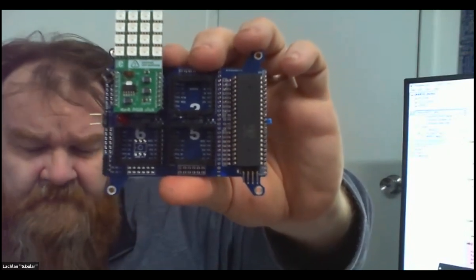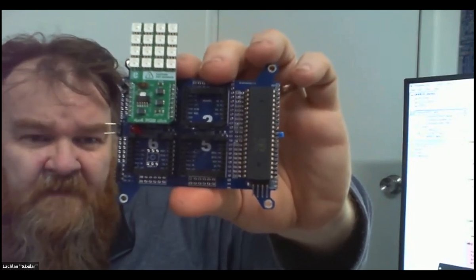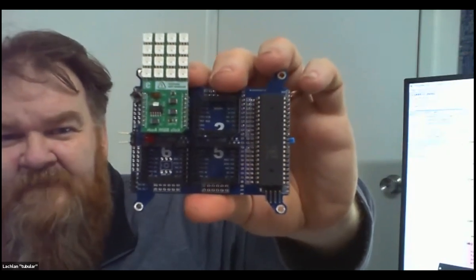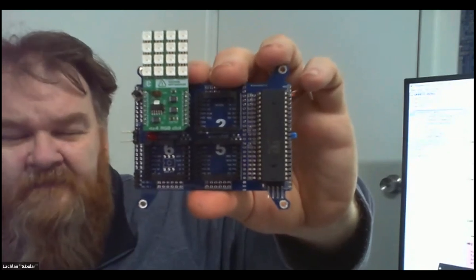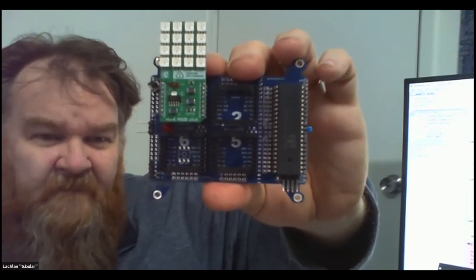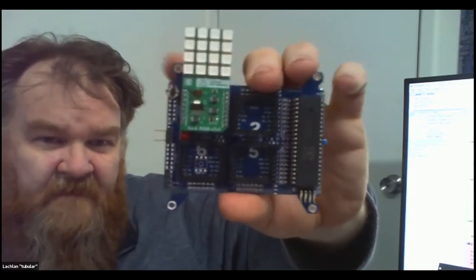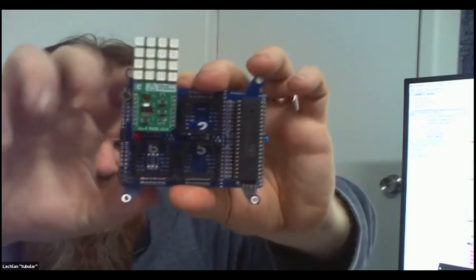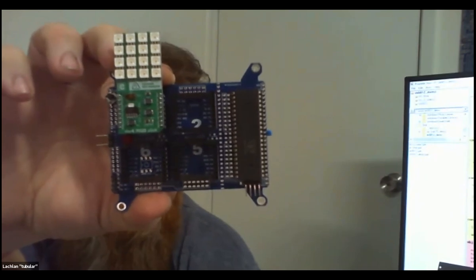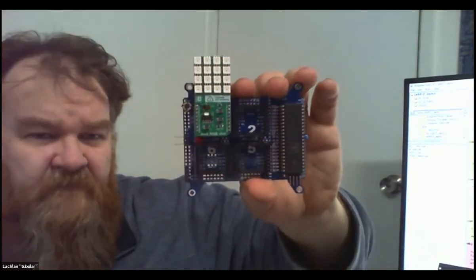And so with the P2, Chip was far-sighted enough to put in that right into the loader so that when you're doing a prop text or a prop hex loading command, you can set an address mask, and that means your code will only go to a particular module or a few modules which have a matching address which match the mask. So the idea is that when we cascade these, and we've put some IO pins on the corners which will enable this to be connected to the next, at least the prop plug bus, so to speak, will be connected across modules, go to the next one in line. So we'll be able to sort of address individual boards if we want to.